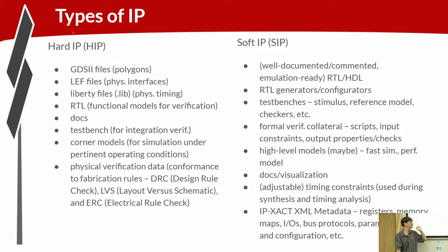When we do design, it's pretty rare that we're designing anything from scratch, coding up all the RTL for the whole chip. The methodology today is basically that you have teams working on IP blocks, and teams building chips by integrating these IP blocks together, maybe adding a little of their own secret sauce. The IP can be delivered in two main ways, soft or hard. Soft IP is delivered as RTL. Hard IP is delivered for a particular technology, maybe as the GDS2 file for that IP.